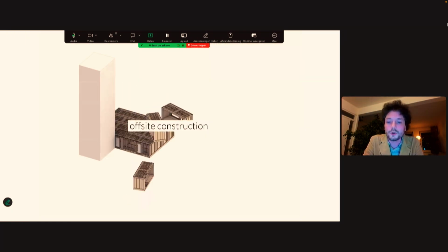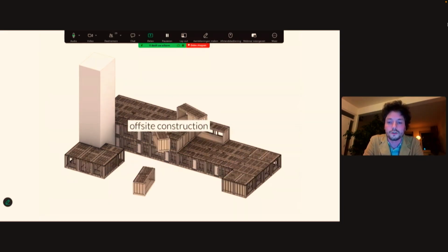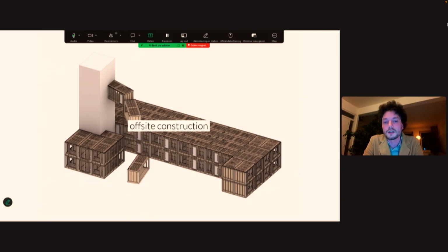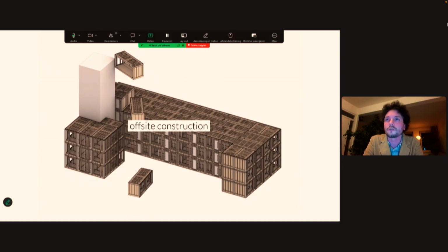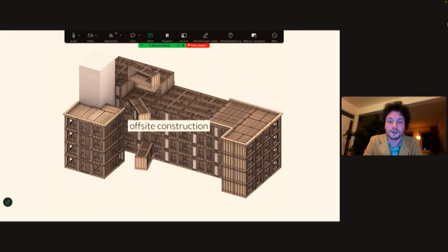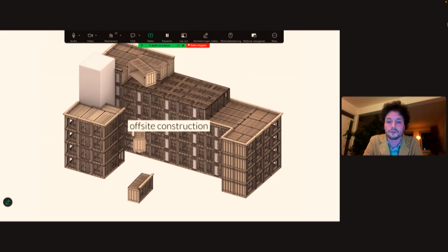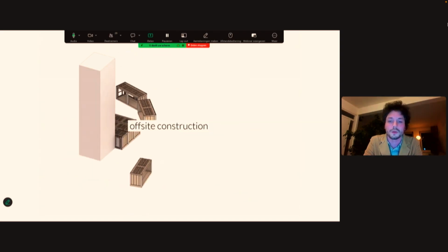We assemble those buildings in about 15 minutes per module. It's a 3D modular system, and therefore you can build about 8 houses in an apartment building per day, and then a whole building like this in a few days. Of course, it depends a bit on the other elements like foundation, etc., which have to be on site before.